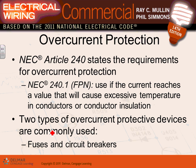So if you guys go to Article 240, Article 240 will tell you equipment and feeders, branch circuits, and service entrance conductors have to be protected based on their ampacity. So that's very simple. If you have a panel, you have to protect the panel with an overcurrent protection device. If you have a conductor, you have to protect that conductor based on its own ampacity. When we protect them, gentlemen, we use either a fuse or a circuit breaker. A lot of us in the engineering community use a lot of circuit breakers, and fuses have a lot of application too when it comes to protecting equipment.